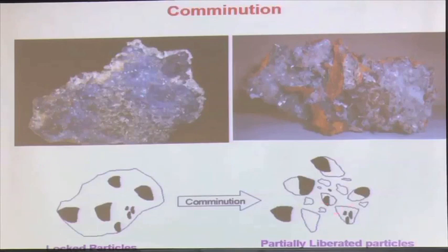So, if I want all the particles to be free from each other, that is black and white segregation, then these particles have to be broken to very fine sizes. By doing that, you consume more energy to break them. Energy means cost, and as the sizes become finer and finer, which in this course we will discuss, your processing cost also goes up, and your environmental problems become more and more difficult to deal with. So, there is an optimized condition I have to look at.